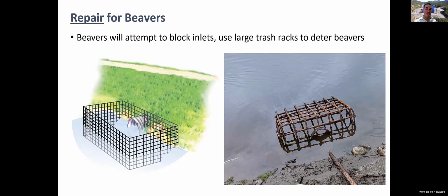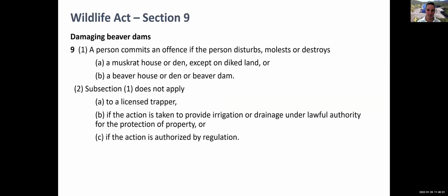It's also a stability guideline in BC, 2-to-1 minimum downstream, 3-to-1 upstream. So that's really good guidance. Also having trash racks that serve a purpose as kind of beaver blockers. For smaller dams, there are different perforated pipe type designs. So it really depends on what your application is and what your flow requirements are, what works. And even sometimes these big trash racks work quite well for slide gates. There are lots of examples, lots of design guidance.